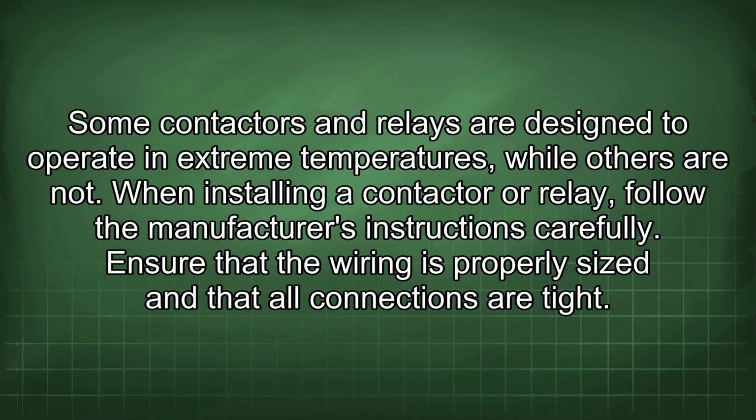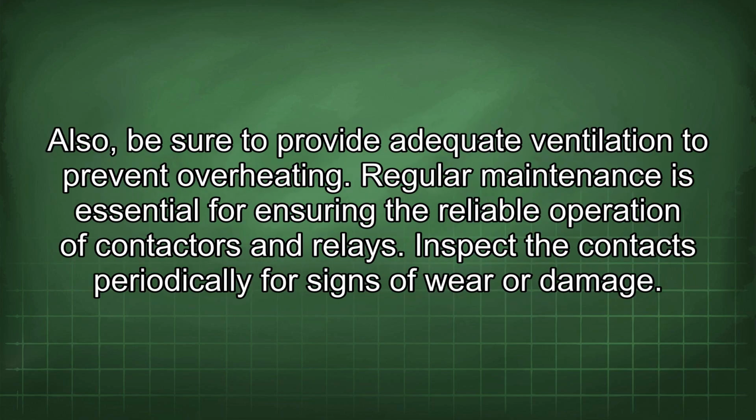When installing a contactor or relay, follow the manufacturer's instructions carefully. Ensure that the wiring is properly sized and that all connections are tight. Also, be sure to provide adequate ventilation to prevent overheating.